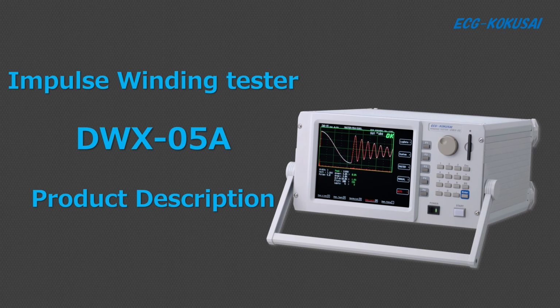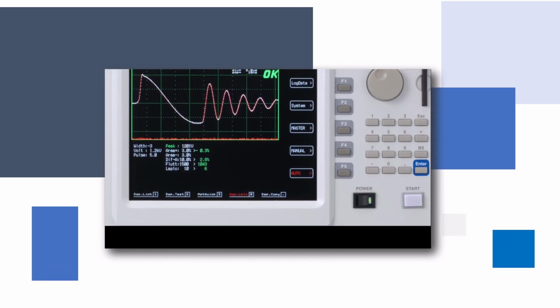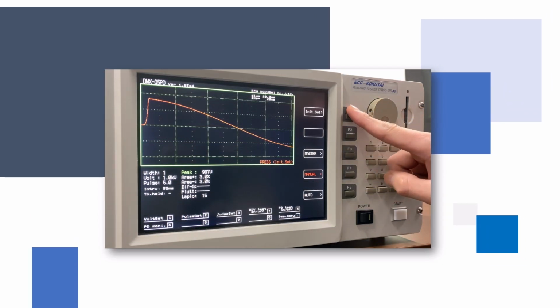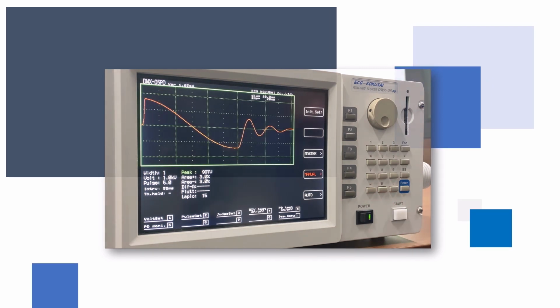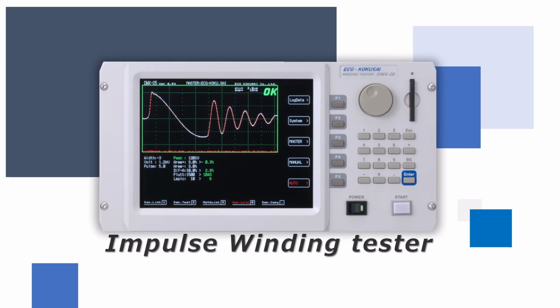This video provides an overview of the impulse winding tester. The impulse winding tester efficiently conducts electrical testing of coils in a non-destructive manner. It applies the same impulse voltage to both a standard coil and the coil under test, then compares their transient waveforms to determine pass or fail.